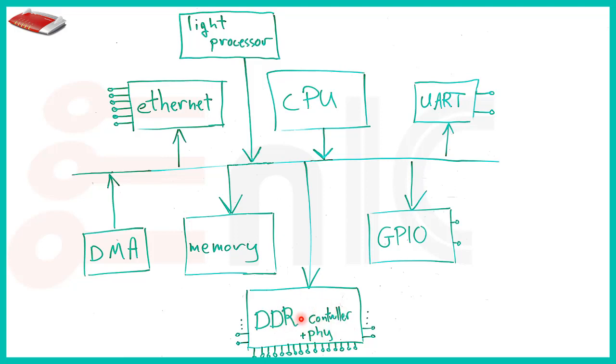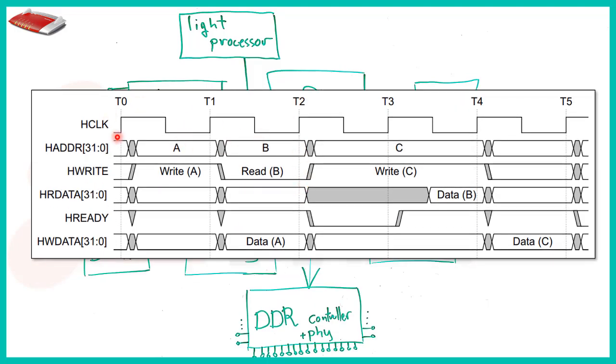And the DDR controller enables us to reorder the different accesses to the DRAM in order to maximize our throughput and take care of these row accesses and column accesses much better. So how do we actually do this reordering? I mean, it's really strange. If we discussed our AHB before, that was our high-speed interface that we were using. Everything was in the end ordered. We'd write data, we'd get the answer, we'd read data, we'd get the answer. So everything was really in order.